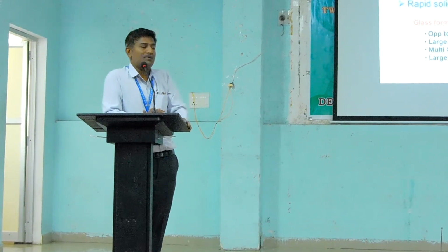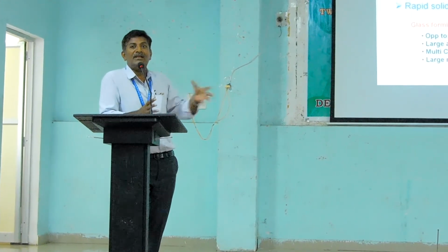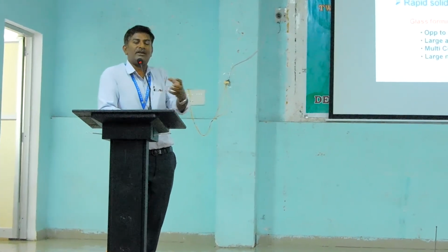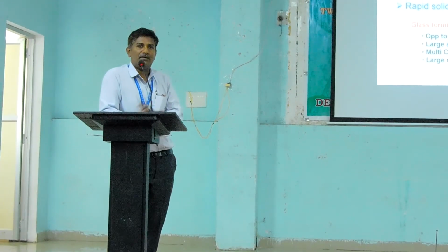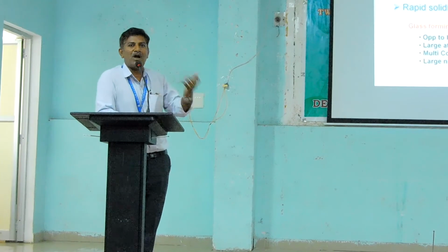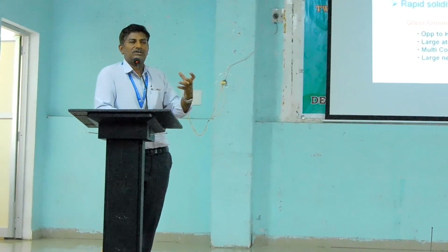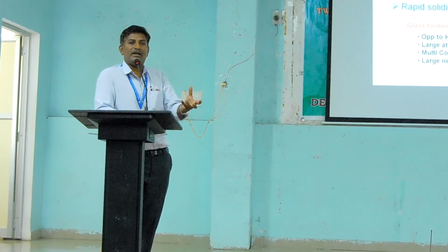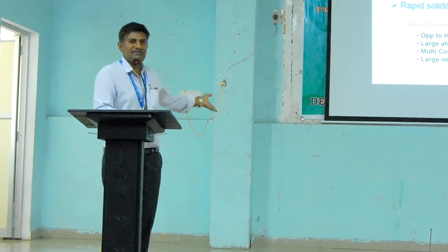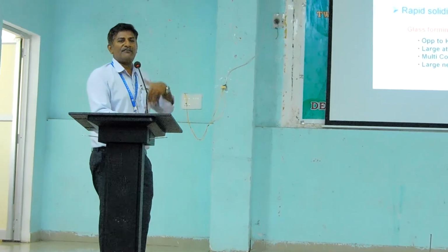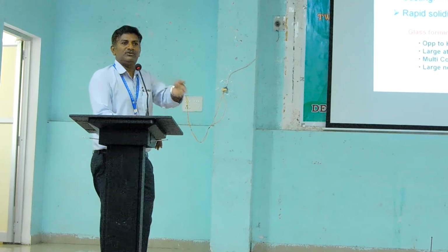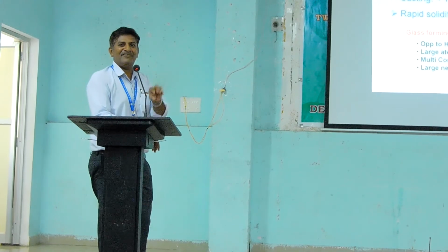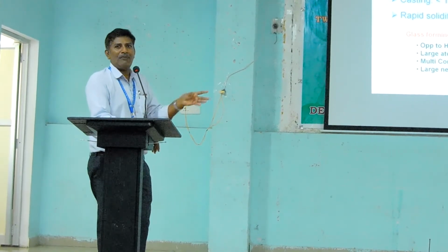So this is the eutectic system. What I want to tell you is, when you have a very high negative heat of mixing, you will find eutectics. And eutectics are the best systems where you can form amorphous phases. So we are discussing how to make a nanomaterial. Making an initial amorphous material and then trying to crystallize it to a nanomaterial has many advantages, which I'll show you subsequently. These are areas of research where you will come across in future. I just want to give a brief introduction, a feel about these systems. Next.